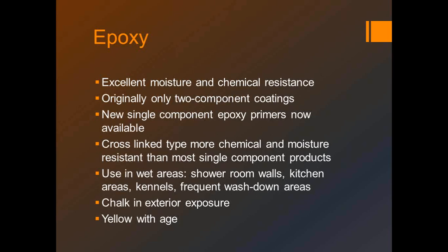It really kind of depends on the drywall. A water-based epoxy, a 2-component polyamide water-based epoxy, would be a good system over it. I like to use a 100% acrylic primer just so you get some better holdout with epoxy finishes, but that would do very well. You don't necessarily have to use a solvent-based epoxy these days. We do have water-based, 2-component water-based epoxies, and then there are new single-component pre-catalyzed epoxy ester, not epoxy ester, let me get my terminology straight, acrylic epoxy systems that you can use too.